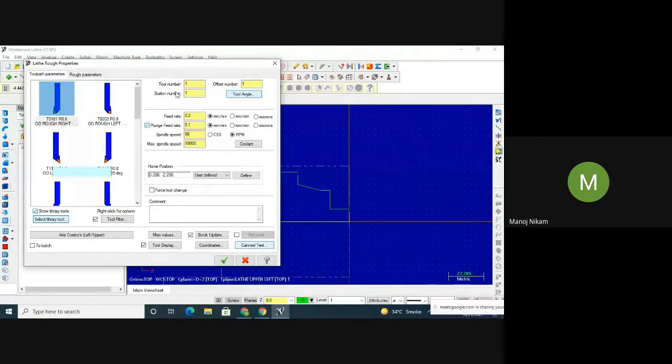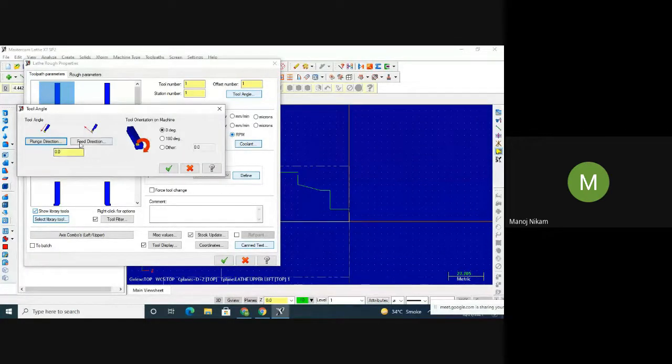So you can see on the right hand side the yellow color is indicating the tool number. So what is the code for the selection of tool number? Anyone? M06. M06 T0. So this number will be the one. So whatever is in front of T, when we generate the G code and M code, at that time you will see the values over there. Now you can see the offset number. Okay, so the offset number, like the offset which we are going to provide in the radius compensation. Okay, so that offset is mentioned here.